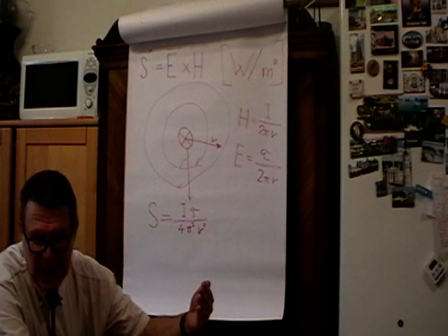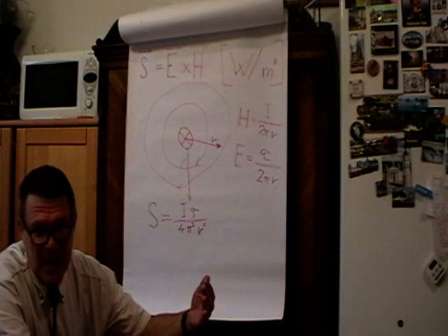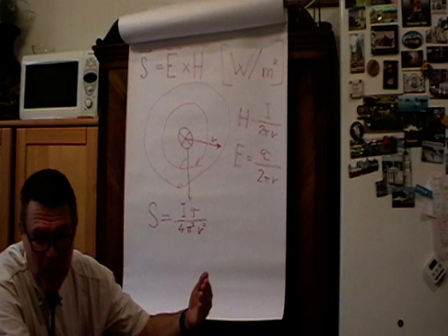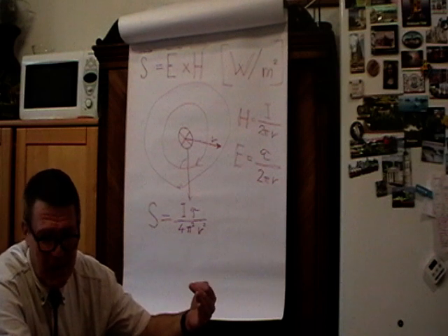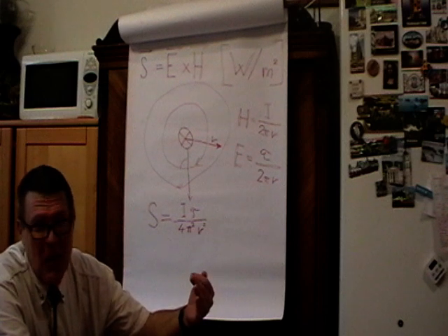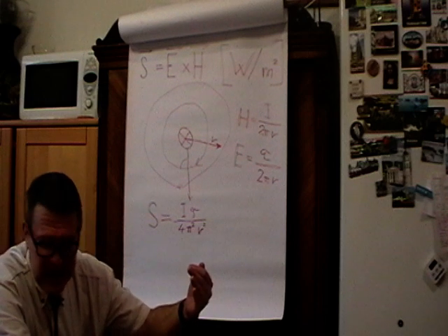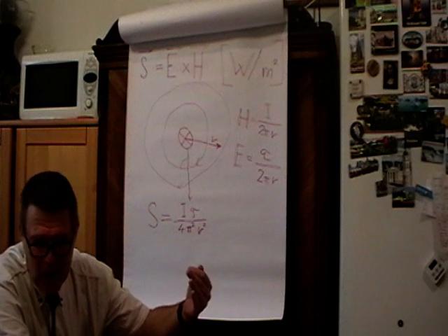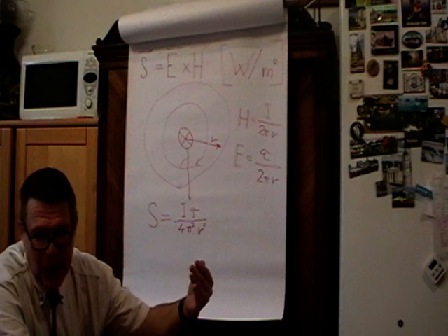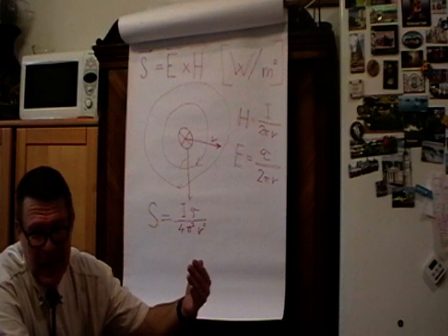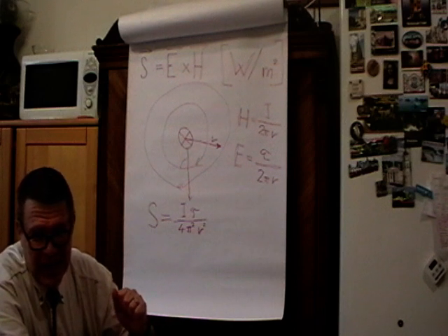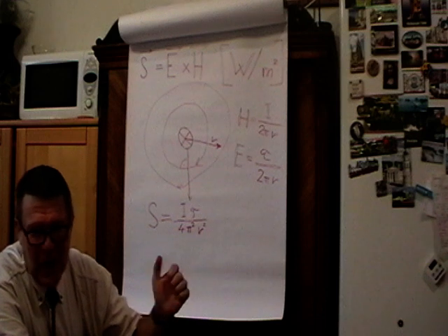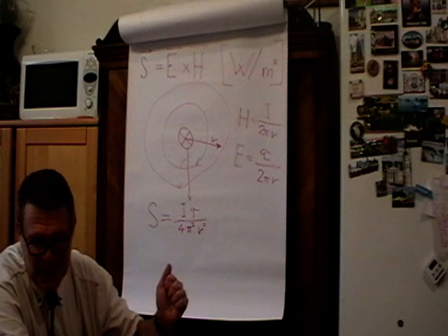But you as electrical engineers should know that this is not the case. The power is distributed along the conductors. It runs around them with biggest density just at the conductor surface, but it stays out of the conductor. And as I will show you later, we try to keep it out of the conductor for good reasons.